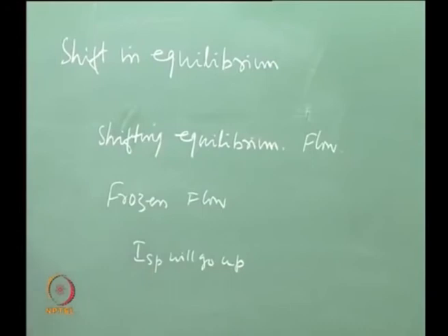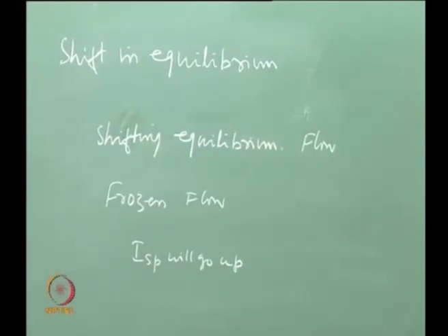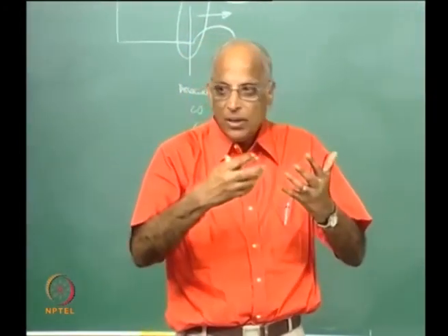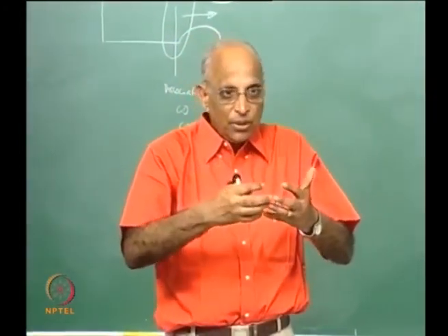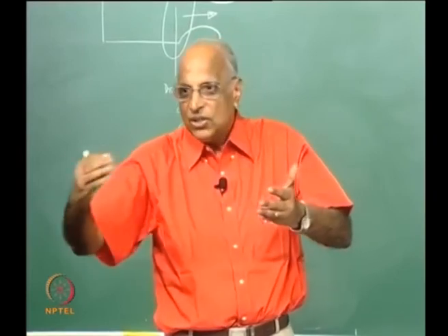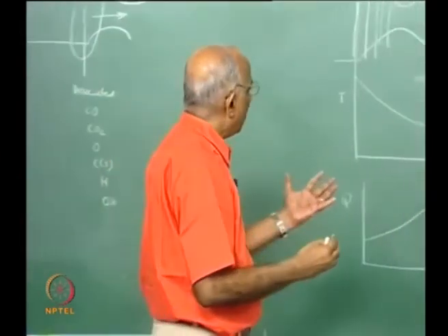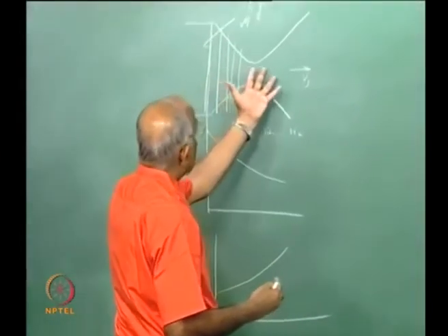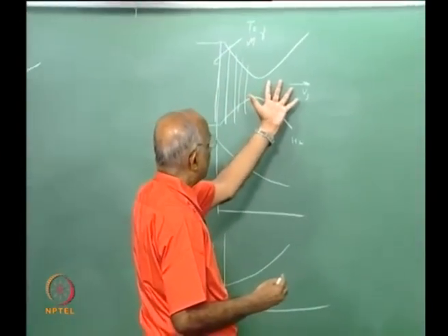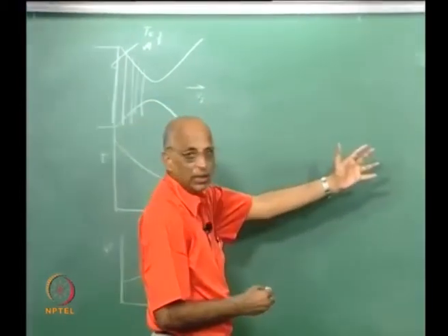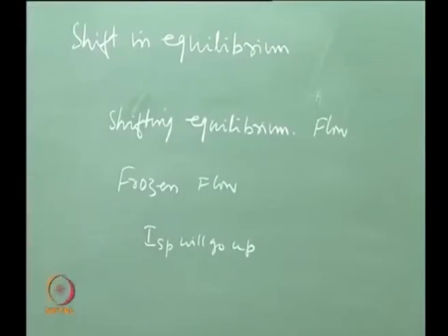I think I have to consider this in further detail with some figures for you, but therefore a nozzle flow is not that simple after all. If I have chemical reactions taking place, because the equilibrium is changing at each particular point, I get heat release taking place at each particular point, and therefore recombination takes place, giving me a net higher value of the specific impulse. We will keep this in mind. Let us do a problem.